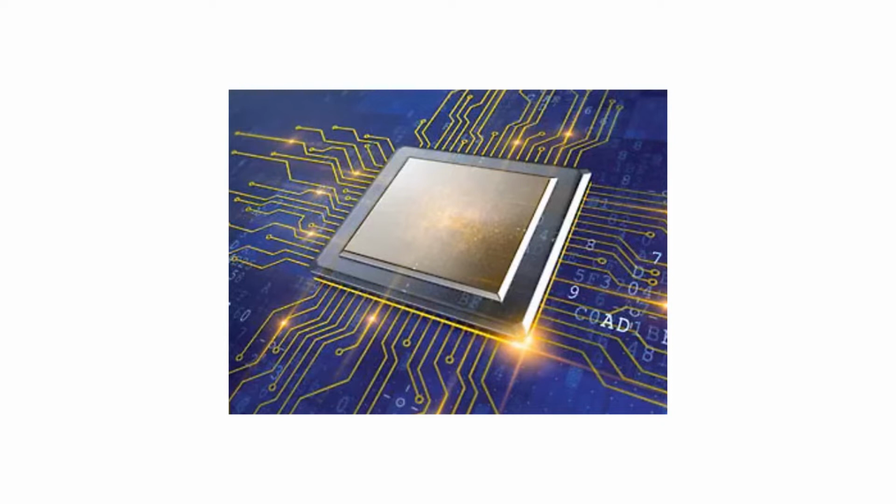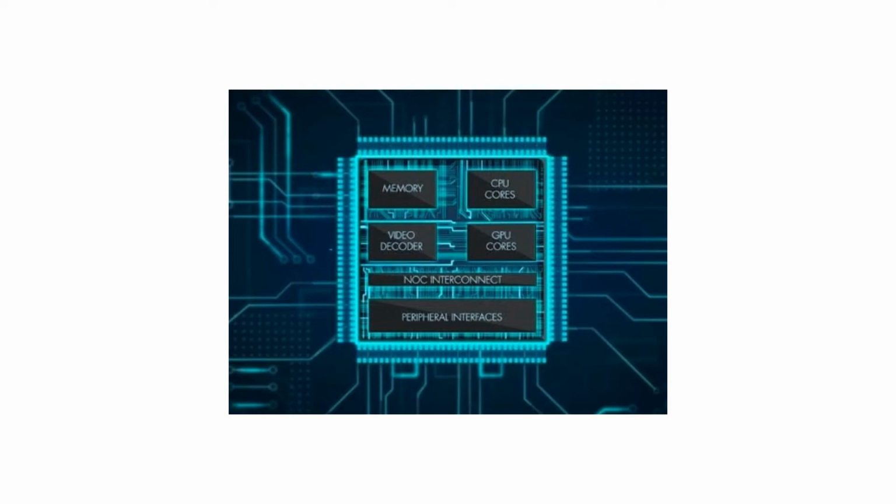In this part 2, we will figure out some more details on EM. EM, as you know, occurs in any conductor where the current density is higher than the limit it can withstand. In an SOC design there are multiple places where it can occur, in signal lines, that is signal EM, or in the power lines. We will learn more about it further.